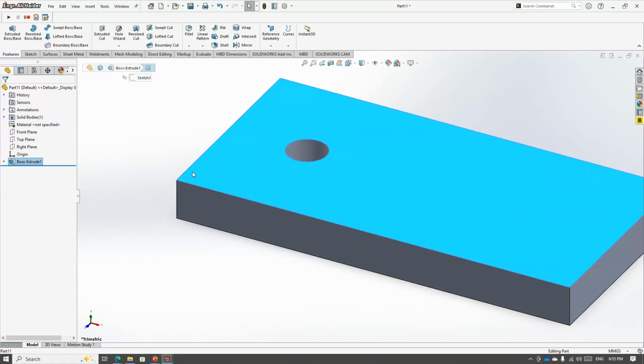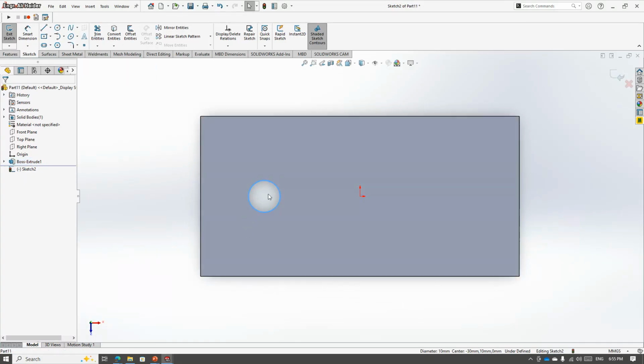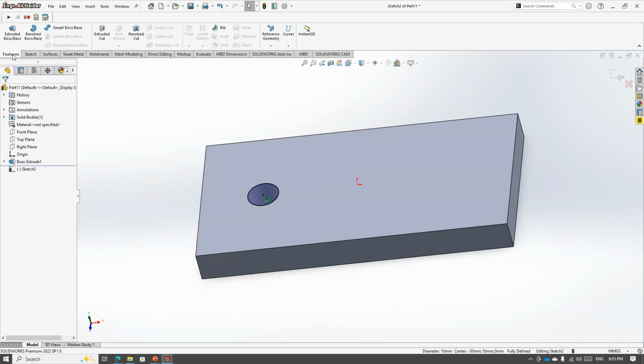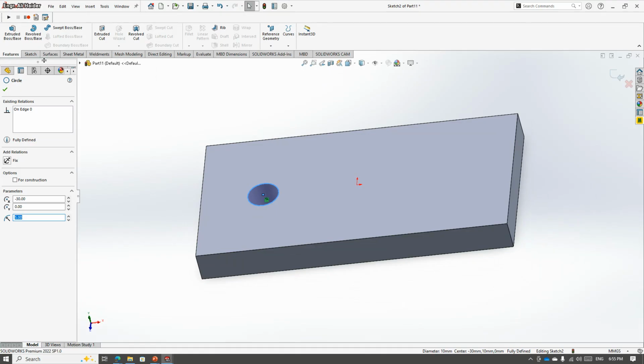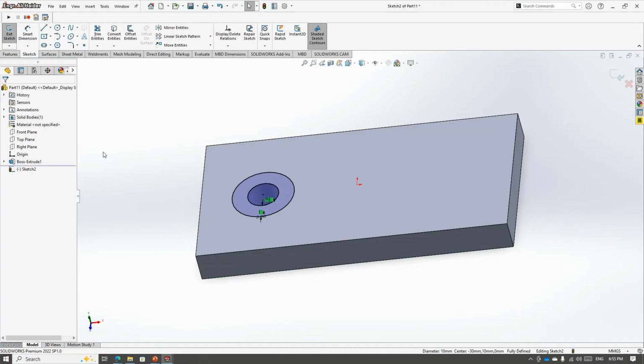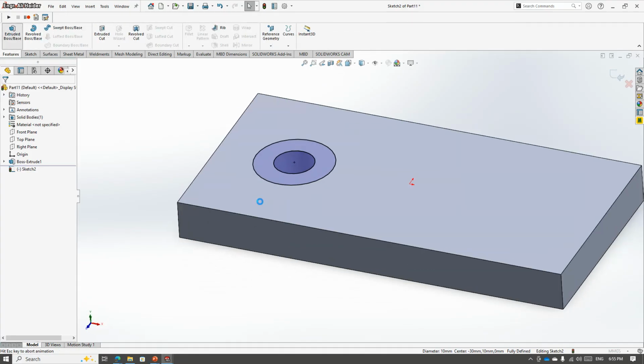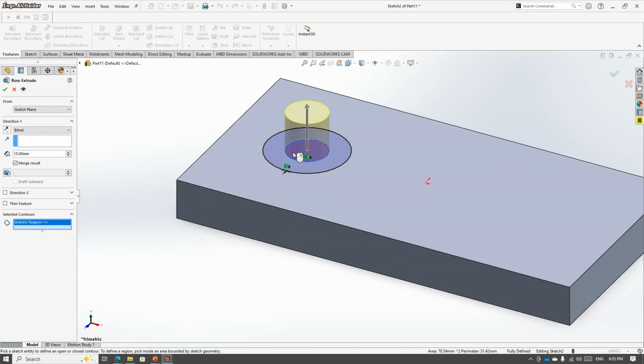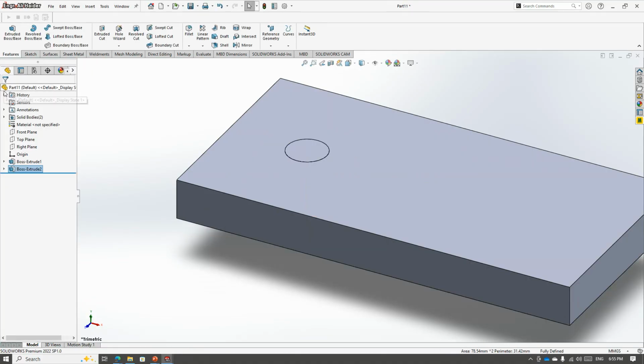And I also want to create a bolt. I will simply select the face, convert it up, and I also want to create the head, so I will again convert this to 5 mm and click OK. So I will extrude from the contours. I will simply select the inner surface, rotate it up, move it 20 mm. And when we are going to create a multi-body, then we must uncheck this mark. If we select merge, it will create a single part. We need to create a multi-body, so we'll unmerge this, click on OK.